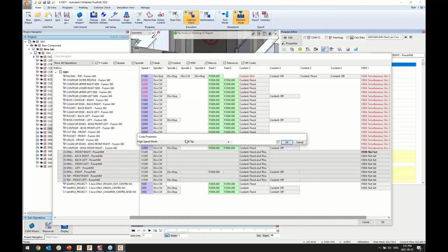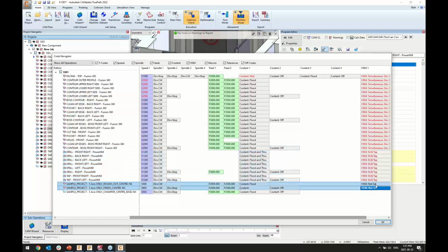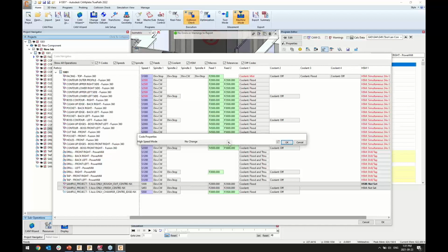Obviously, there will be more focus on drilling and tapping, which will have different focus and different settings internally in the controller. And ultimately, some of those operations at the end are, again, focused more so on the 5-axis type of thing. So very different, again, machining objective, very different machine behaviors. At the beginning, we're really focused on heavy 3-axis material removal, plunging the tool, removing as much as we can.